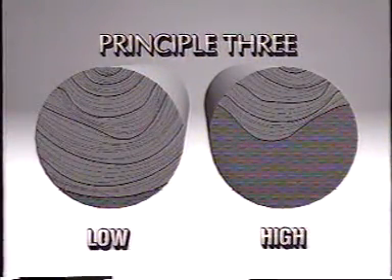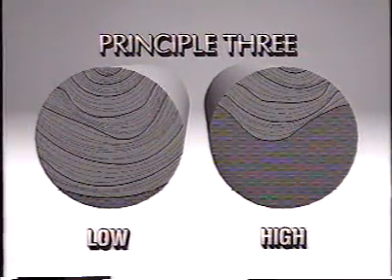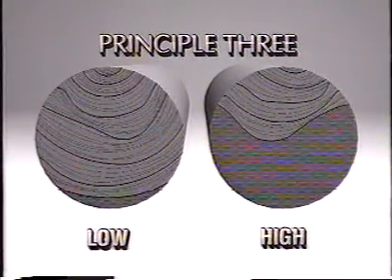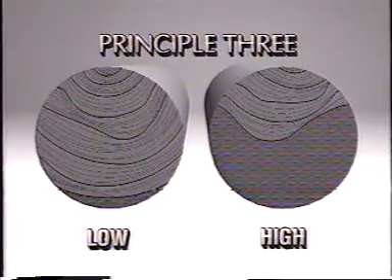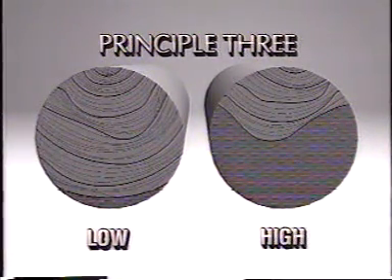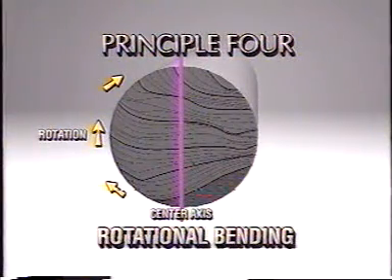Three. With an overload slightly more than adequate to cause a fatigue fracture, the region of final fast fracture will be relatively small. Under a much higher applied stress, this region will be relatively large. Four. In a fracture caused by rotational bending, the final fracture region will often be offset in a direction opposite to the rotation.